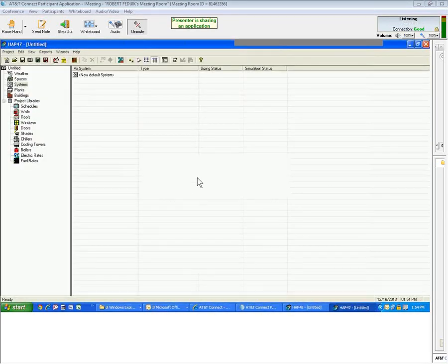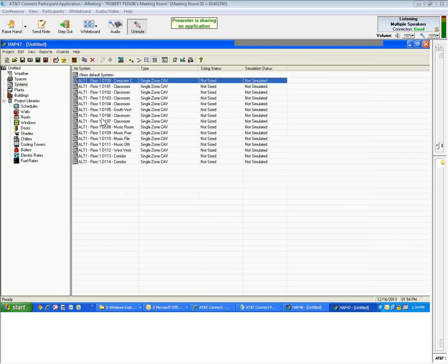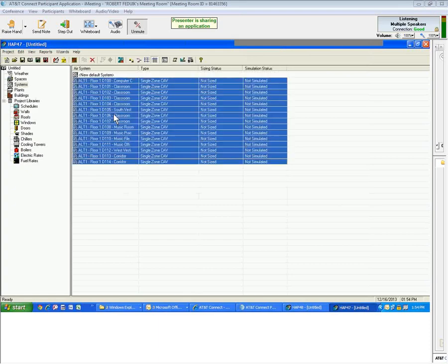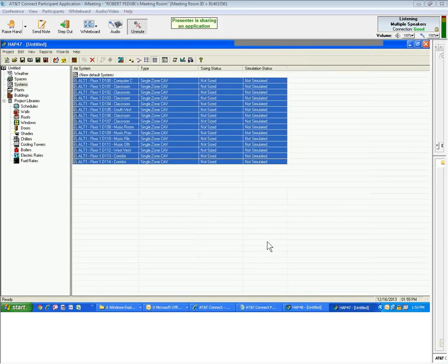Now at the air system level, I've got 15 air systems all ready to, I could run the loads now, shift, click, highlight, print your design results, and run 15 loads on 15 different rooftops. Get the answers. And we'll go ahead and do that. So the wizards are a streamlined way of doing the basic HAP functionality. Now, we crammed a lot in.